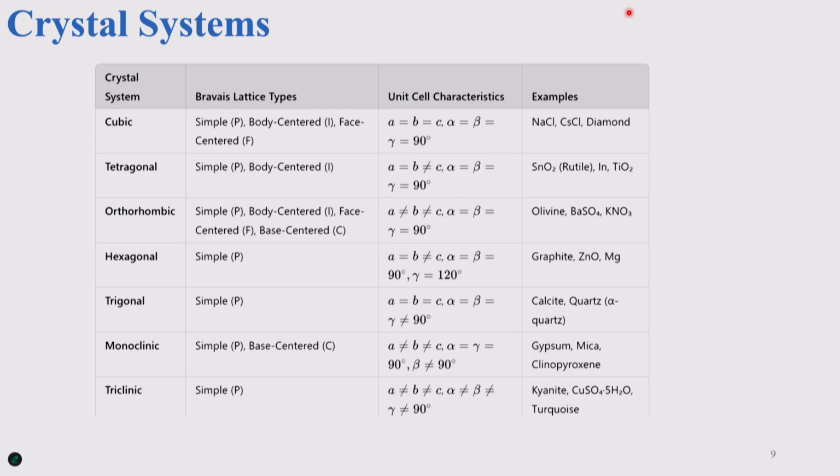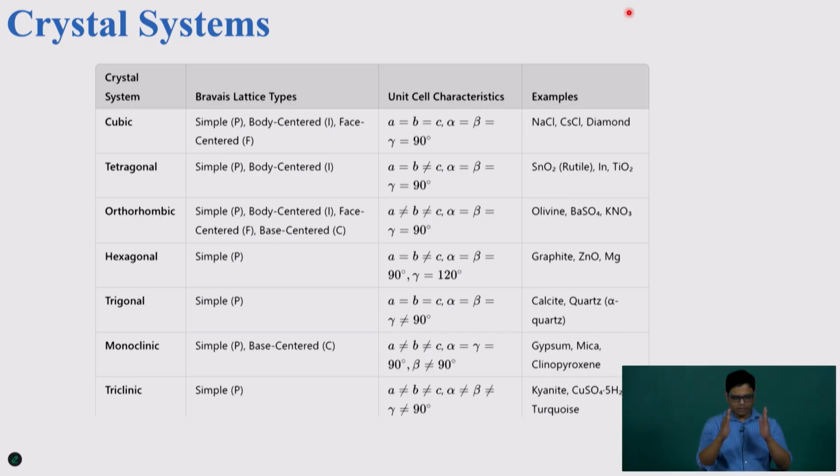So we saw that silicon structure, right? How they have this kind of 3D structure. They are characterized by the a, b, c lattice constants and the alpha, beta, gamma angles. And how do we have them? Whether a equals b equals c and alpha, beta, gamma are 90, that's a cubic material like rock salt, and so on. Based on this structure, again, the property will be decided. It's very important to understand the structure of the material, right? How many of you have seen this kind of Bravais lattice and stuff? Please raise your hand. Almost all of you. So I don't need to spend too much time on this.